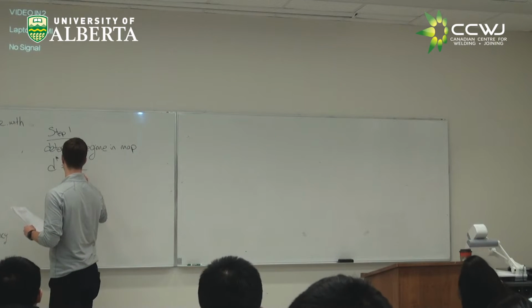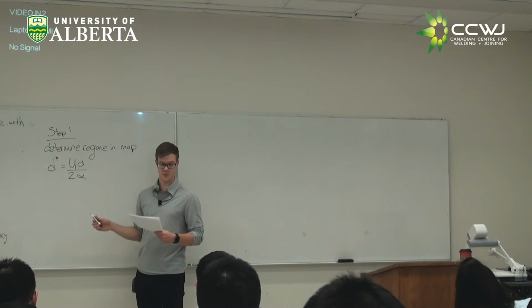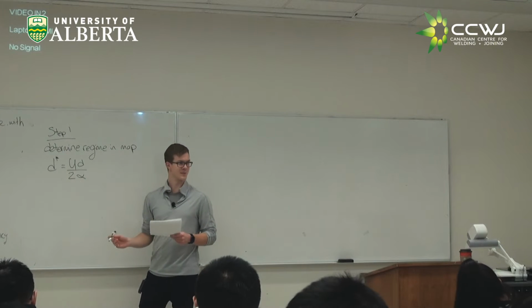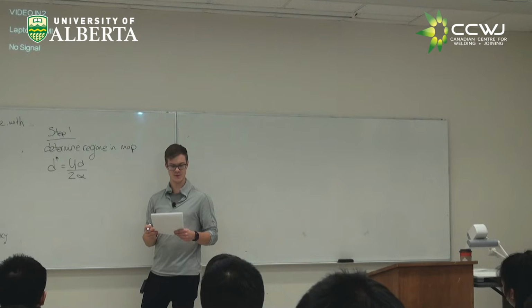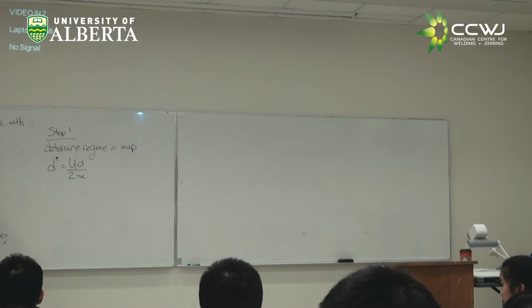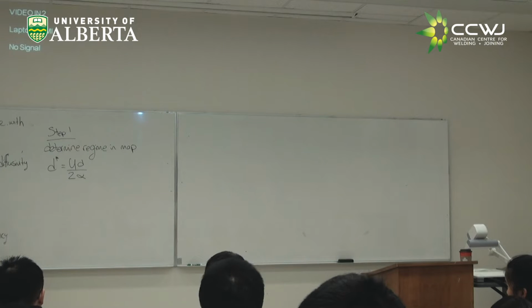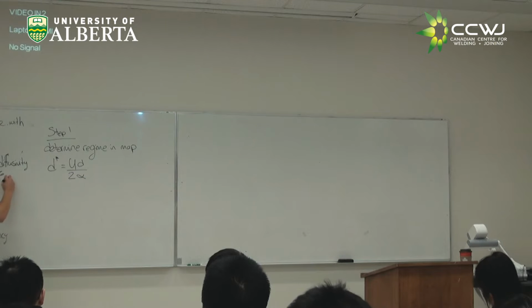So, U we have from our procedure, D we have is 25 millimeters. Alpha. Does anyone have a rough number of what alpha would be for steel? Alpha is going to be our thermal diffusivity, right? 0.1. Awesome. And does anyone have units for that? Meters squared per second. Perfect.